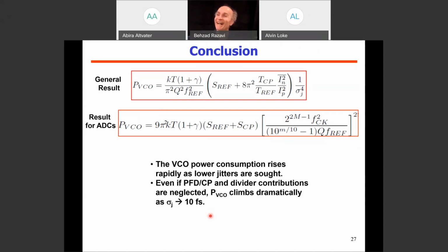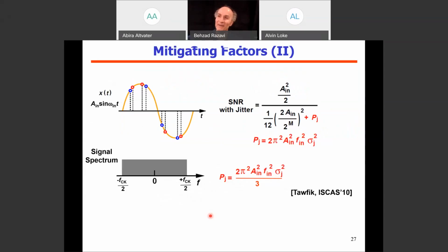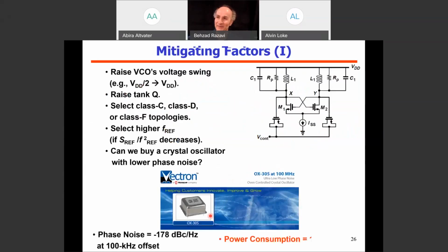The question, the oscillator that you presented with the minus 178 dBc per hertz phase noise shows that these usually run at high voltages like 5 volts and 10 volts, but when it comes to CMOS operating at 1 volt, the phase noise at minus 170 would go higher. Can you comment on this? Yes, absolutely. Yes, I agree.